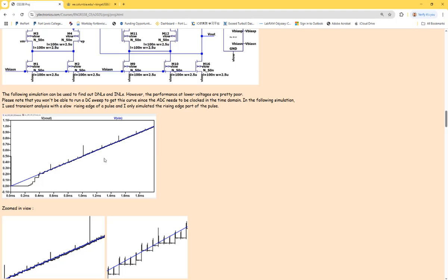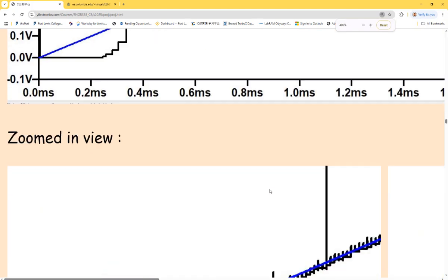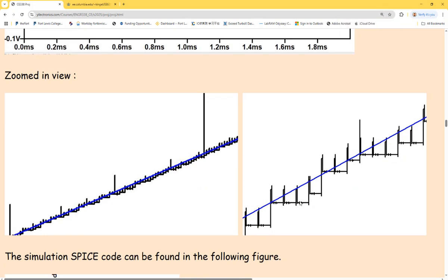So you are going to run a simulation like this, and you can see this curve, and I zoomed in, and I zoomed in further. It looks like this. You just have to figure out a way to make it fit, right? Which point you are looking at. So I was measuring the ADC's step size. It's about 0.6 millivolts, and ideally it should be 0.4 millivolts.